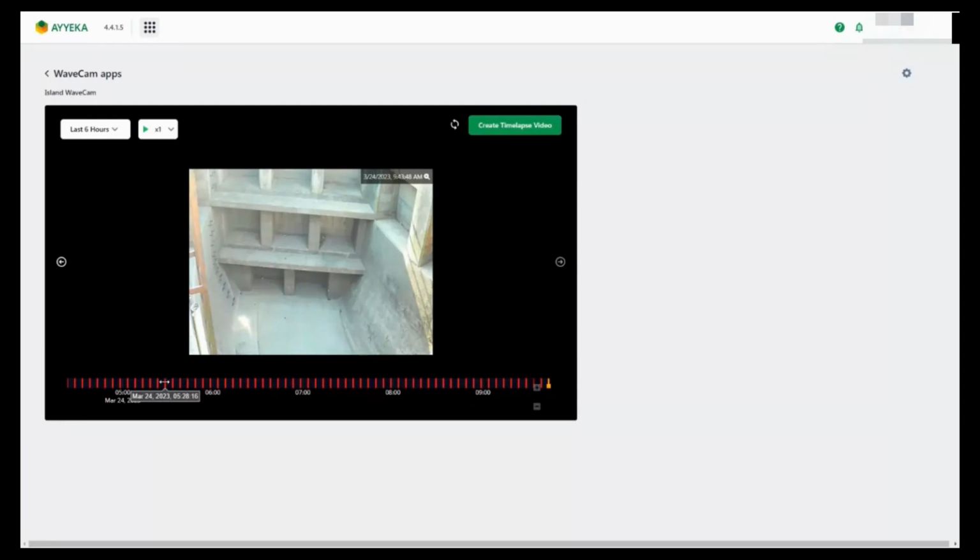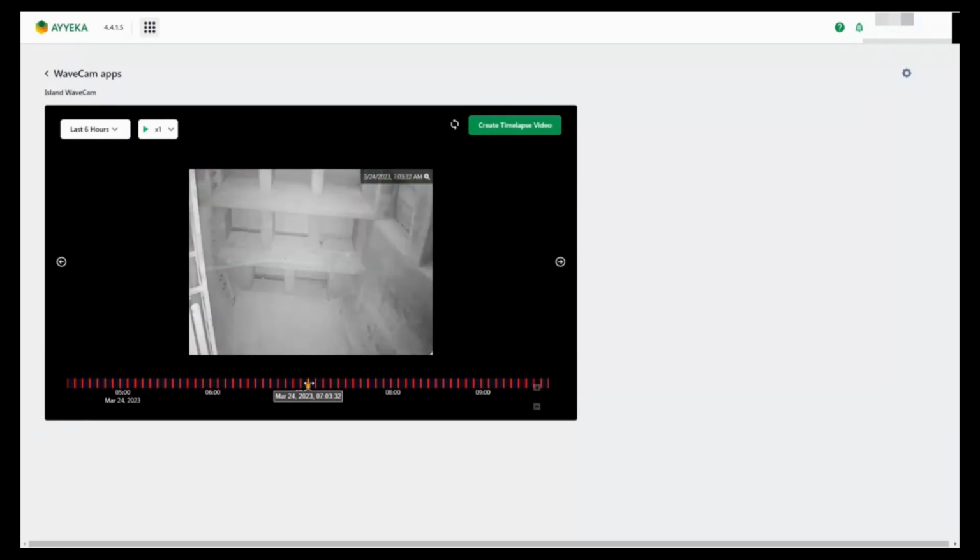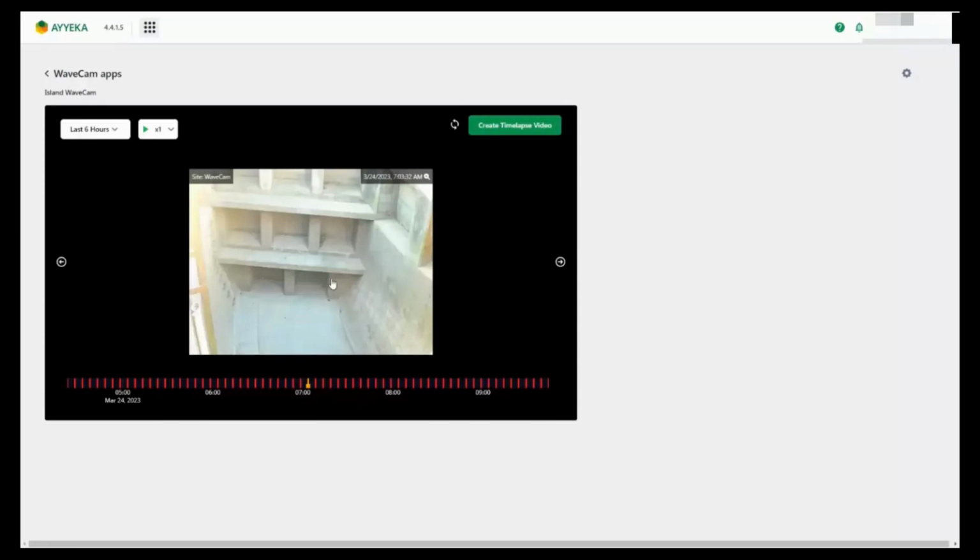You can configure the frequency at which we take these pictures, and those pictures can also be triggered on an event. For example, if we had a water level sensor here, we could trigger the camera when we detect water in this chamber. And it's very nice to be able to check the real-time situation, because, for example, if we were to have to send a crew out to the field or to open an emergency floodgate, it's sometimes difficult to make this decision just based simply on the data from a sensor.